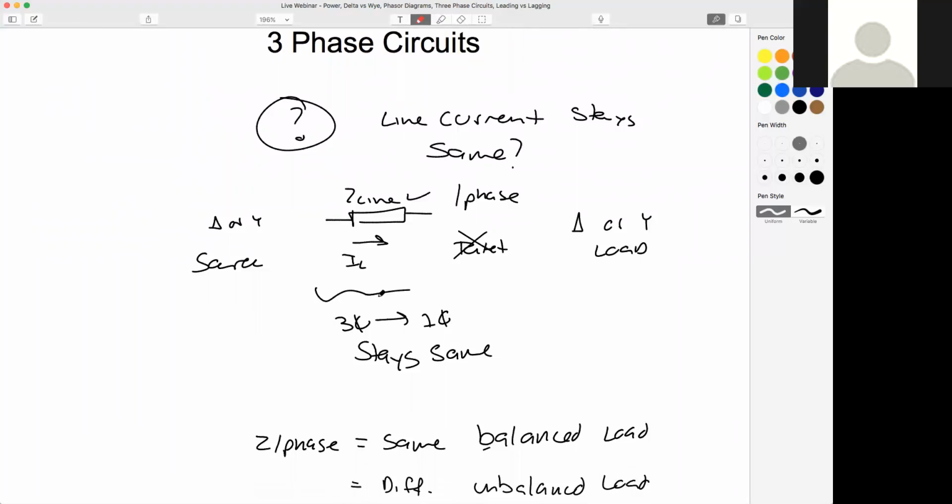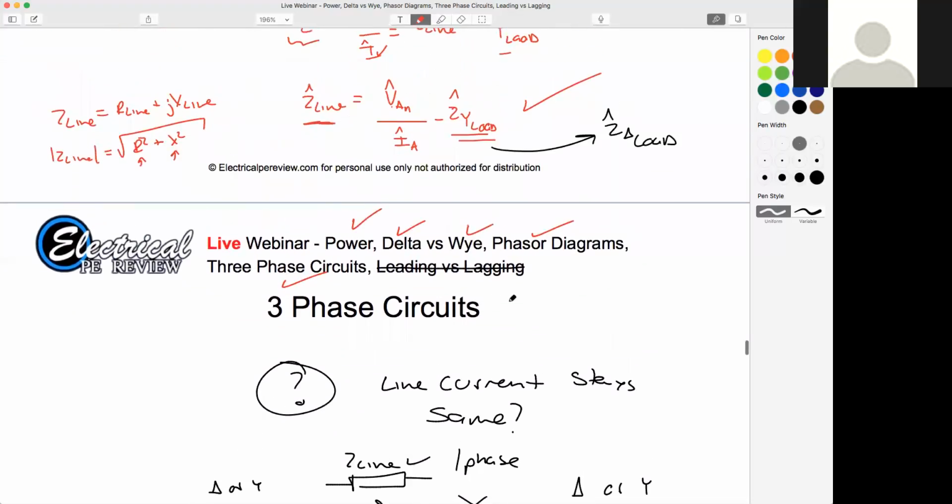Omar, in all caps, shouting at me, said, Zach, out of topic, at voltage drop calculation at transmission line, Z efficiency or Z effective is required to be included always. So careful, Z effective is an approximation of line impedance that they use for calculating the ohm value of an ohm per length times a length value. Typically you get the effective impedance just to find the total value in ohms, right? Because effective impedance is usually our ohms per 1,000 feet or 1 kilometer.